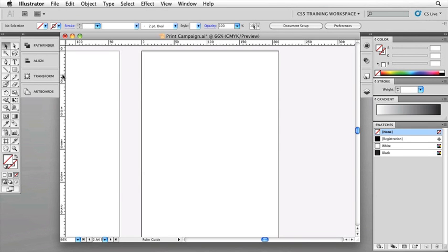Once again, click on the left-hand ruler and drag in, and this time hold down your Shift key, and you'll notice that if you look in your ruler up here towards the top, it's snapping into the increments. Now, depending on your screen size, the size of your document, and indeed your measurement system, you may get different increments than this, but if we're looking at millimeters on this A4 page, we should be getting roughly the same amount. So this is very cool, because I know that this is precisely 50 millimeters into the page, so if I back up 1, 2, 3, 4 increments, and these are 5 millimeters at a time, I know I can drop that at precisely 30 millimeters across.